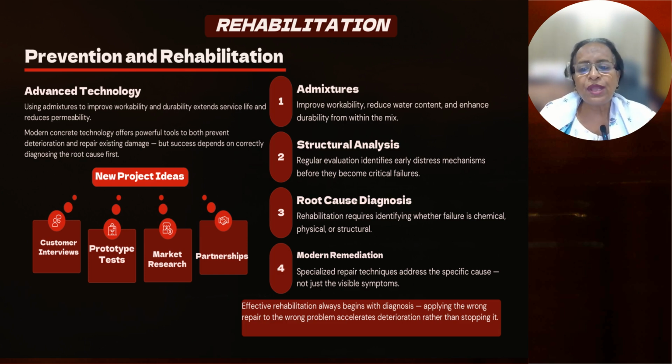Did you know many rehabilitation projects fail because the visible damage was repaired, but the underlying deterioration mechanism continued unchecked? The result, same defect reappears, often faster than before. Practical takeaway: never ask, how do we repair this? First, ask, why did this happen? The quality of the diagnosis determines the quality of the solution.